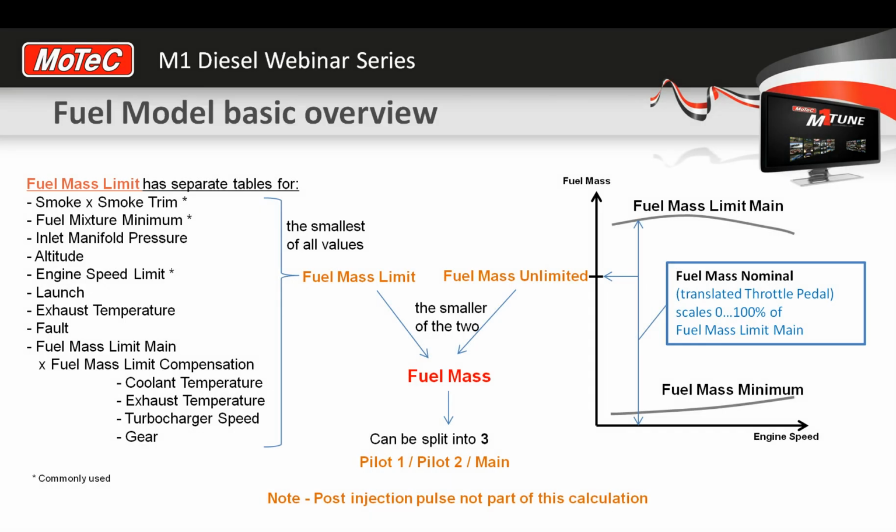Alright, so now this is a bit of a flow chart of the fuel model, and what I'd suggest is that it might be worth printing this out and putting it on your laptop so you can keep track of what's happening. As you start tuning, you're always looking at why perhaps the fueling isn't what you thought it would be, and where the current fuel numbers are being derived from.